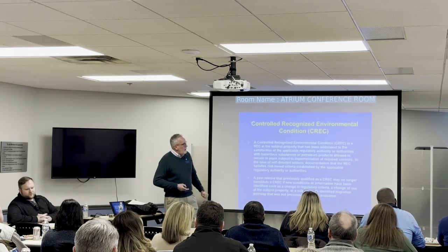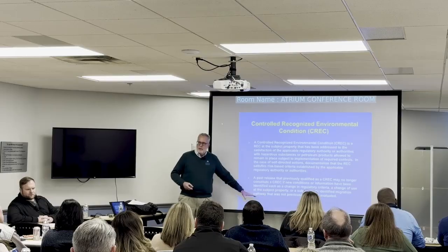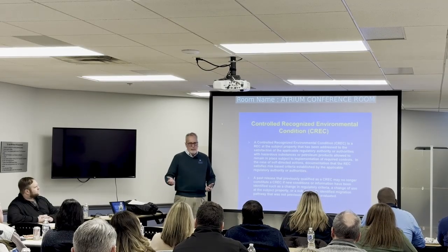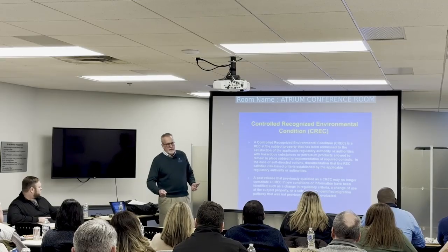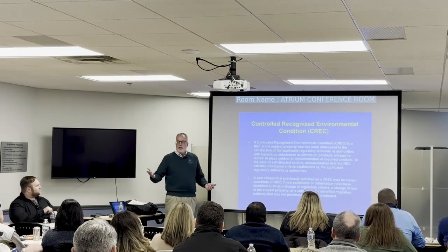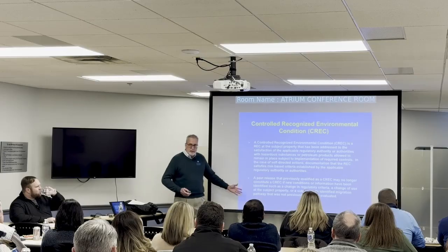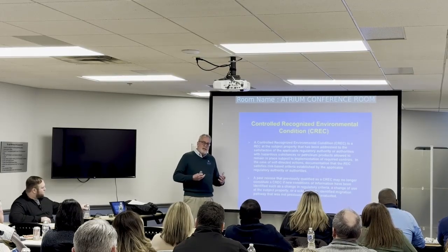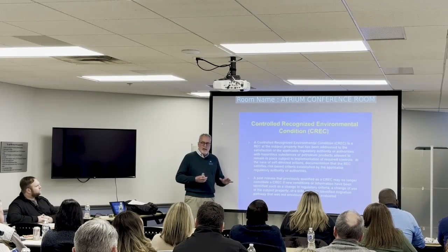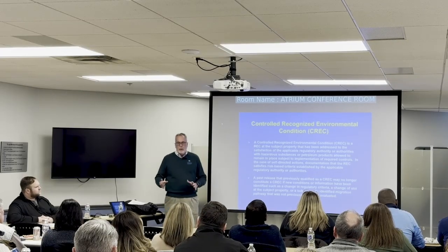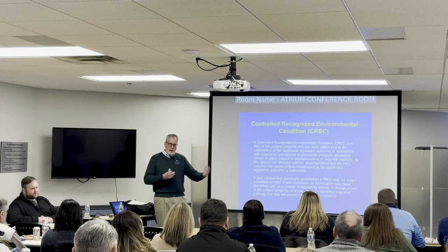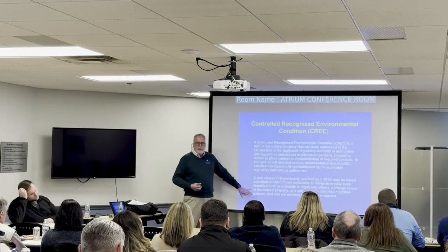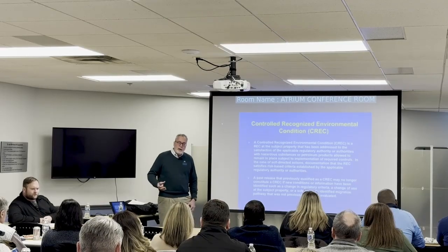So we've got 25 years of underground storage tank closure assessment reports, NFAs, and as the lender, you're like, we've got an NFA on this site, and we look at the data, and it's like, well, is there trimethylbenzene and naphthalene there above action levels? I'm not saying that's a definite problem. It's a component of gasoline. So if you have no benzene, everything's real clean at the site, chances of having trimethylbenzene and naphthalene are quite low. They're not going to be there by themselves. They would be there with that whole suite of chemicals that makes up gasoline. But that's a problem.